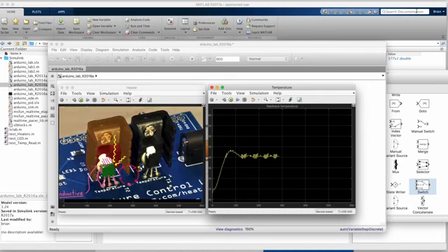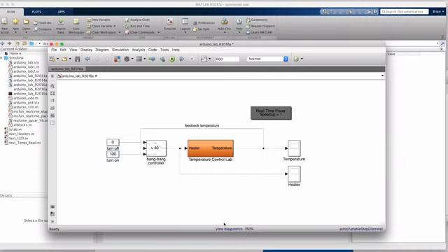Well, the heater will stop getting hotter. The problem is that there's a delay between the heater getting hot and the temp sensor sensing it. The heat has to flow through the thermal epoxy, and so the heater was actually much hotter than 40 degrees when we turned it off, and that extra temperature caused heat to still conduct to the sensor after we turned it off. And I don't like that overshoot, so let's see how to get around it.